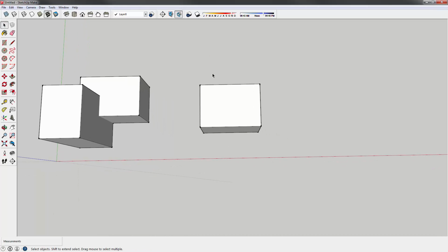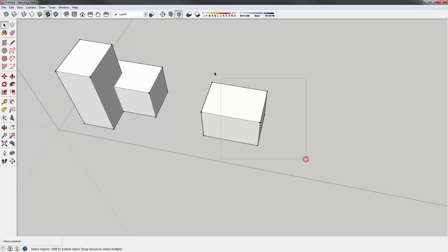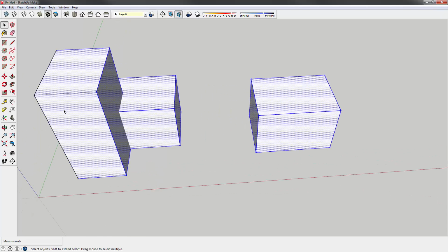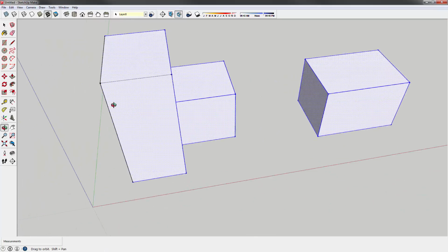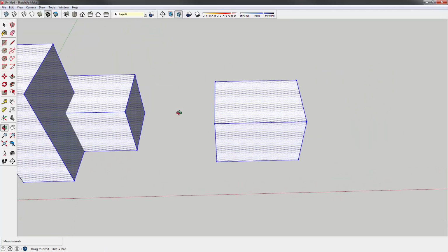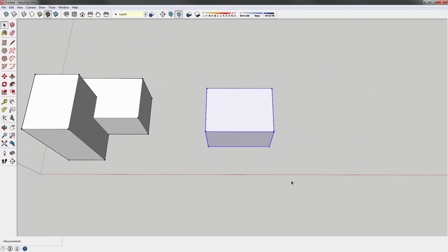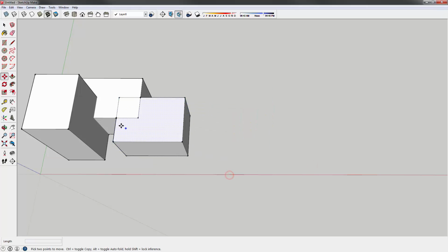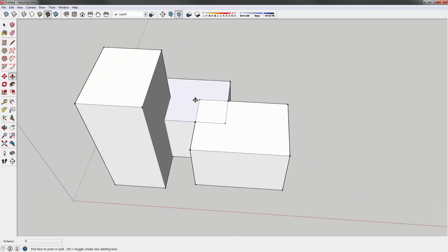So the other way you can do is with the select tool from the lower right to the upper left. Now the big difference here, as you'll see, is that the lower right to the upper left crossing selection method will basically select everything that it crosses, right? So in this case, everything that the square dotted line boundary intersects, it will select. But you'll see that in this case, it selected the faces, but not these edges. Okay, so that can be pretty useful if you're trying to select things together. So I'll just do that. Okay, do it quickly. And let's just pop this out.